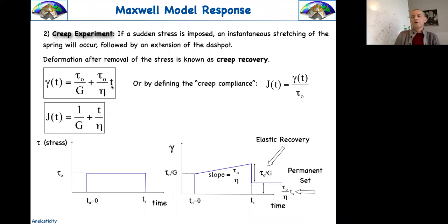So the deformation is going to be the sum of its two elements. This will depend on the time and on viscosity. And now we can imagine making a sort of ratio of the general stress applied and the deformation that we get at the end. And you can imagine that the ratio between stress and strain in this case is going to be this. So this is the modulus, the first viscoelastic modulus relating stress and strain. Again, a check here. If eta is infinite, this will be just the elastic part. If it is zero, the system is going to explode. If eta is something, it will decide the time and so the permanent set to be left. Good, that's Maxwell.